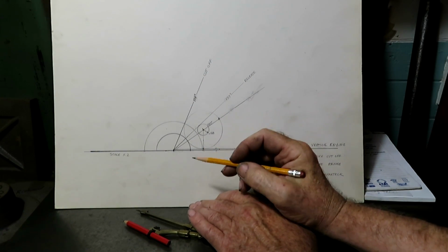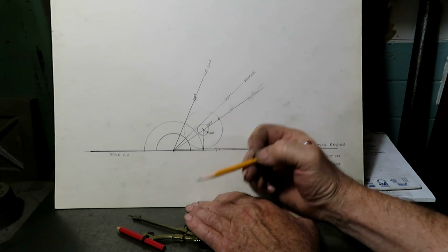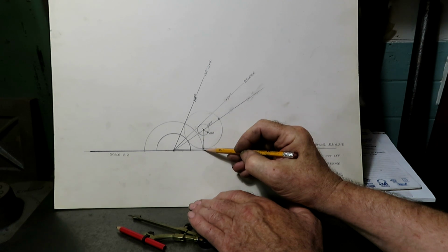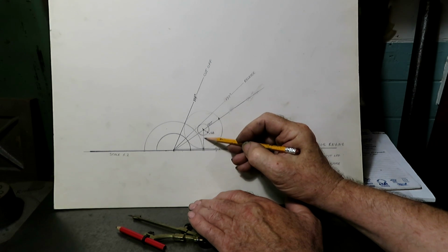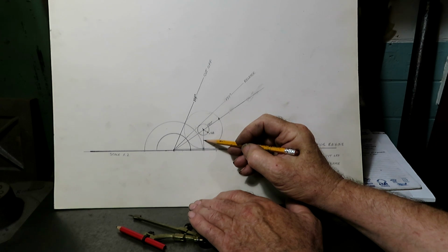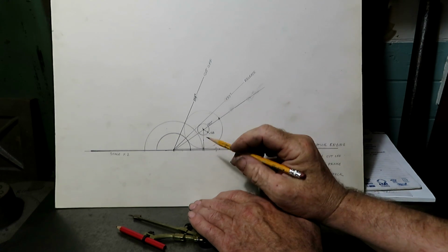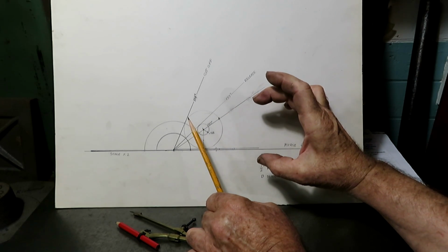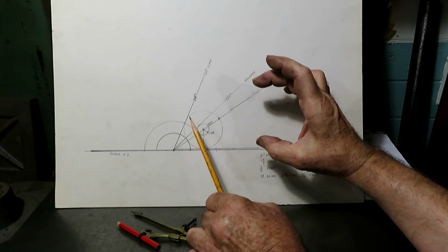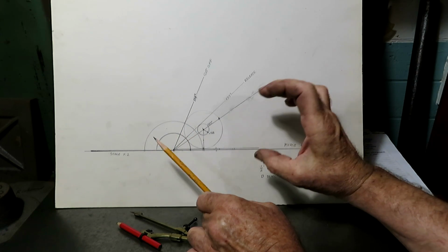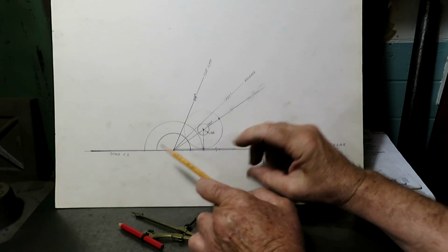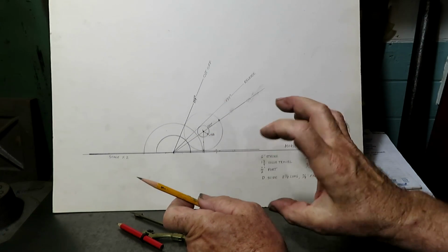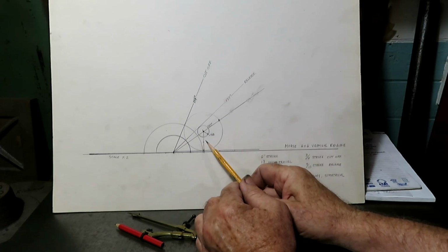So that'll help figure out where we're supposed to be. Oh yeah, one other thing. If you drop a perpendicular down all the way to the bottom here, this distance is directly measured to be the linear advance. And the linear advance is the amount that the slide valve is displaced from its center position when the piston is at top dead center. So that really helps in knowing where the eccentric should be located on the shaft, and I'll show you how that works.